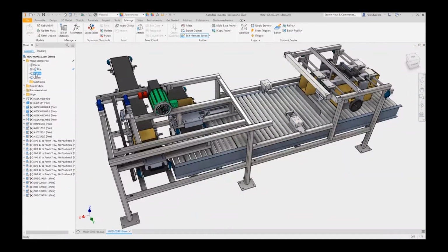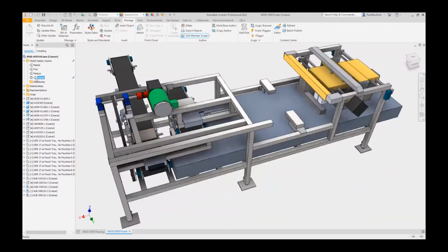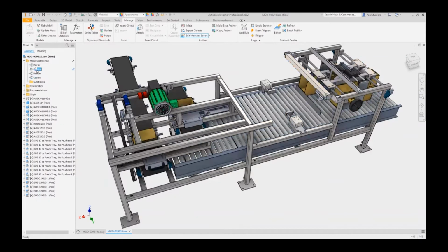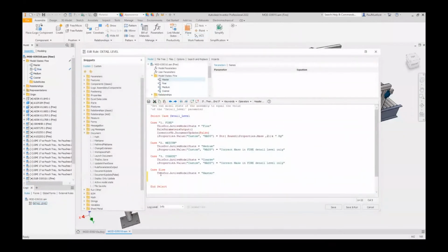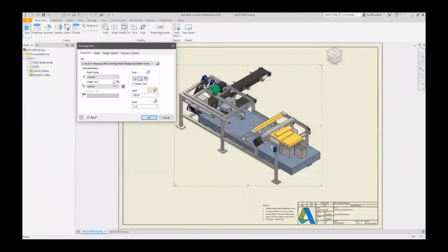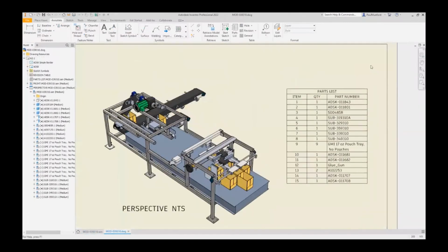Often we need a simplified version of our design for simulation, maybe for coordinating or simply to protect our intellectual property. In the past, we've used automation tools to help simplify designs retrospectively. Model states allow a new possibility of building components that have simplified representations built in from the very start. Simplified representations can be automatically linked to an assembly model or model state, and then provide quick and easy methodologies for simplifying an entire design.